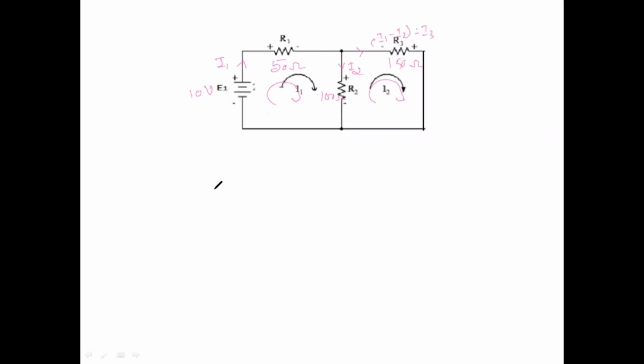If you apply Kirchhoff's law, as I said, there are two loops. We get two equations, and for the first one, you can start from this point. Whenever there is a resistance, there is a voltage drop. So I say negative sign, minus 50 ohms, the resistance, I into R. The voltage drop here is I into R, where I here is I1, and the resistance value is 50.